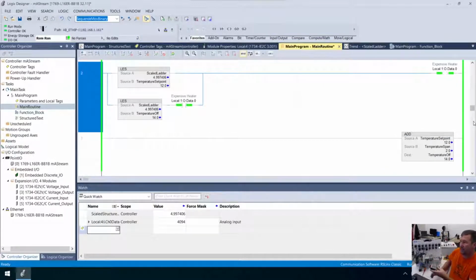But okay, now we're at 5 milliamp and we're looking for 12. Oops, actually, let me go up now because we're heating. So we're bringing this up, and bring it up to 14 milliamps. There, kicks off. So this works exactly the same, only now we are in milliamps instead of the real world values we had. There, kicks on, kicks off, exactly the same.